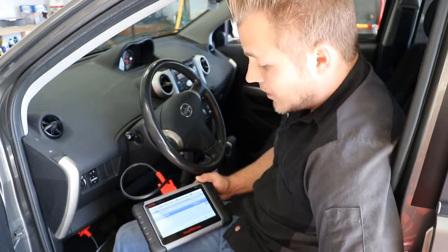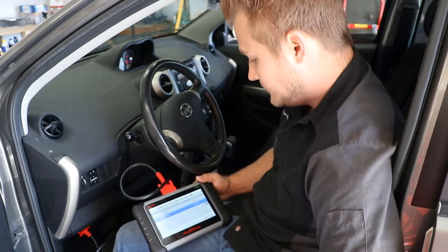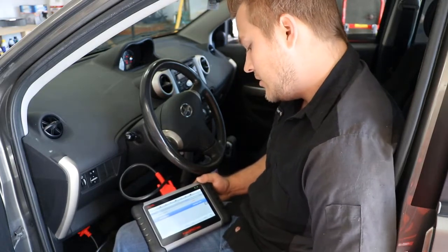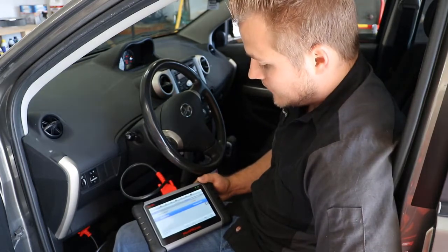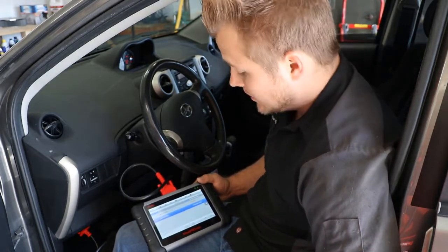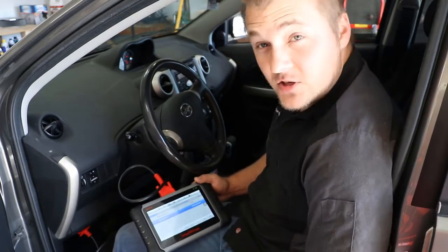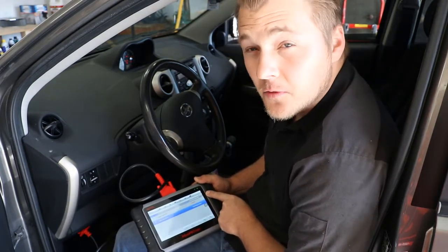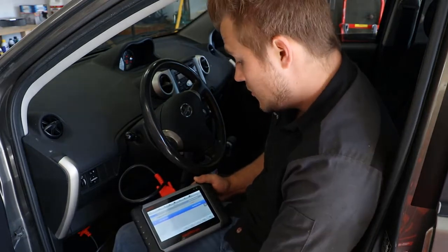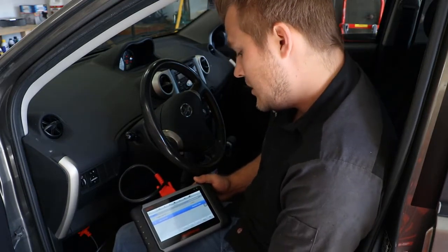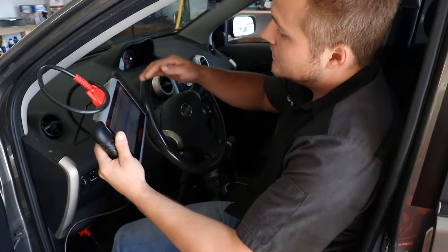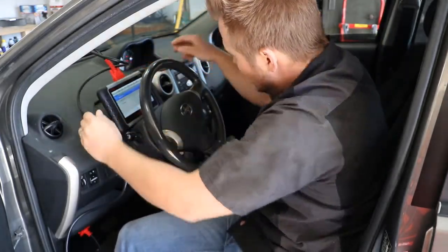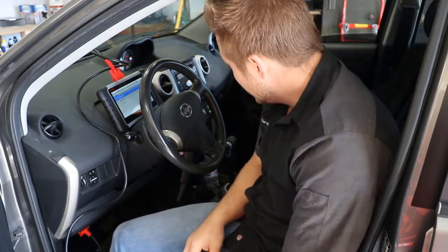Oh, we have 9 fault codes on the engine and ECT. I'm going to check the ABS. Your system's going to be running for a little bit over all of the components of the car. Now, I also like to check the battery in this phase. If you look in the top right, if you have a good scan tool, it'll tell you the volts are 12.38 volts, which means the battery's good. We're holding a good 12 volts. This is scanning for any issues and should be done here in a second.